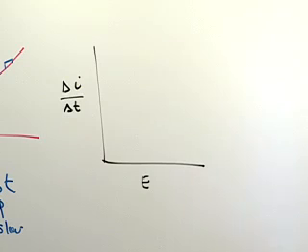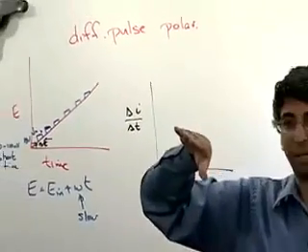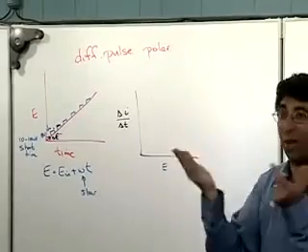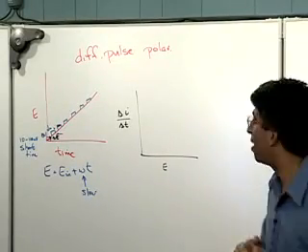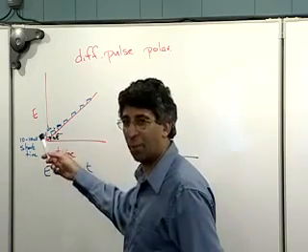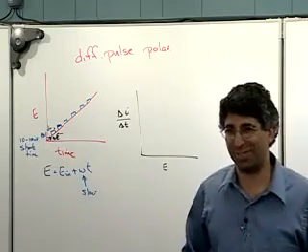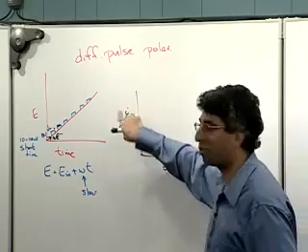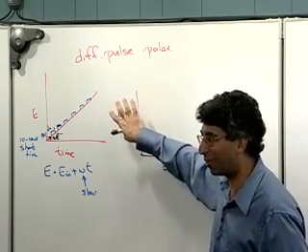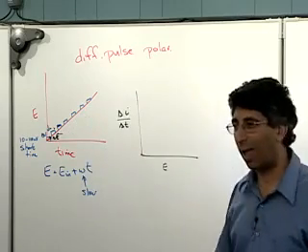And this does two things for you. First of all, by doing the subtraction, if you have an underlying baseline that's getting in the way, it automatically subtracts it out. Okay. And second of all, it just enhances your sensitivity, both to actual signal and to noise, but it enhances your sensitivity, right? Because now you're looking at this differential quantity, or something approaching a differential quantity here.